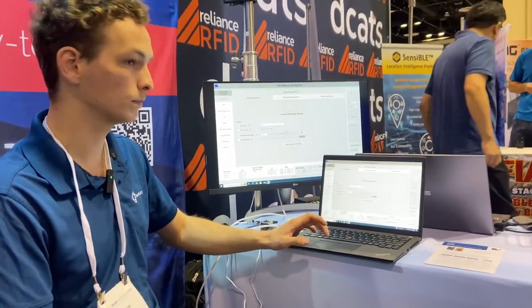So after the configuration is running as desired, it's behaving as they want, this process of burning into the chip, what does that mean? Yeah, so we are one-time program only. We have an eFuse memory. Once you hit the burn button, it is going to burn the eFuse, which is irreversible.